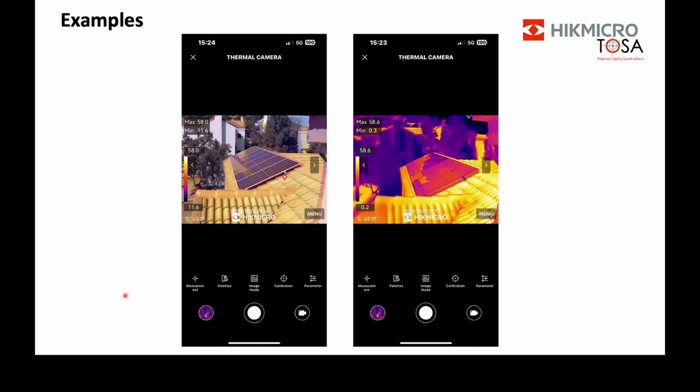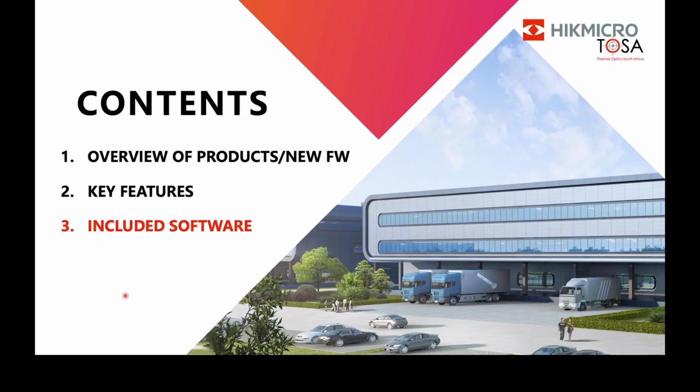There you can quite clearly see that there's some reflection off of the building behind me, and that is what you don't want. For me to do a proper inspection of my panels, I'd probably get on to the other side of the roof there, and then get at a point where I do not get the infrared reflection from the building like you're seeing over there.